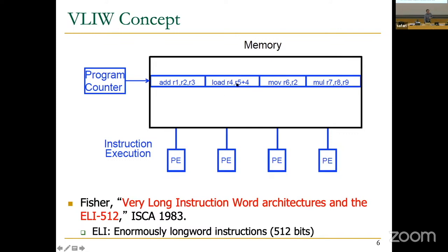So the load instruction is aligned such that when you fetch it, you go to a decoder, and the decoder directly feeds the memory unit. If there was no memory unit over here, the compiler would not put the load in this location. If there was a memory unit over here, the compiler would put the load in this location.